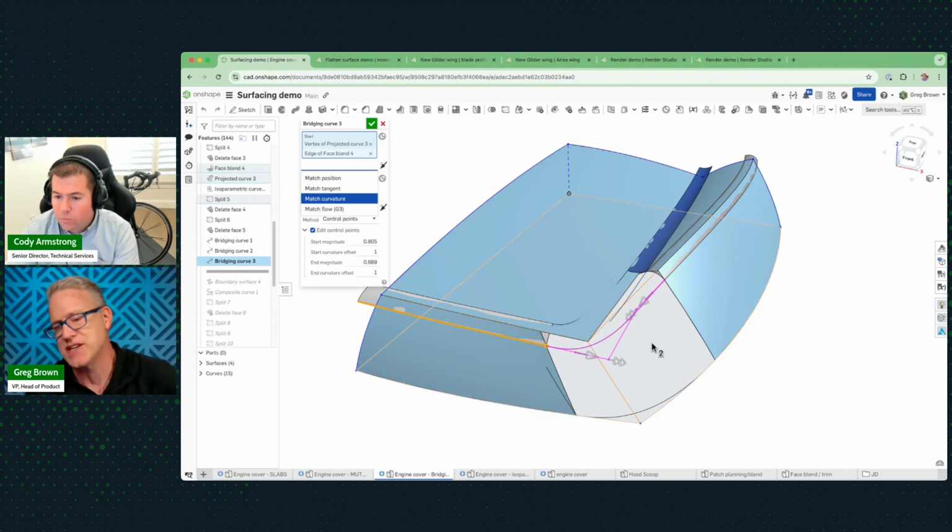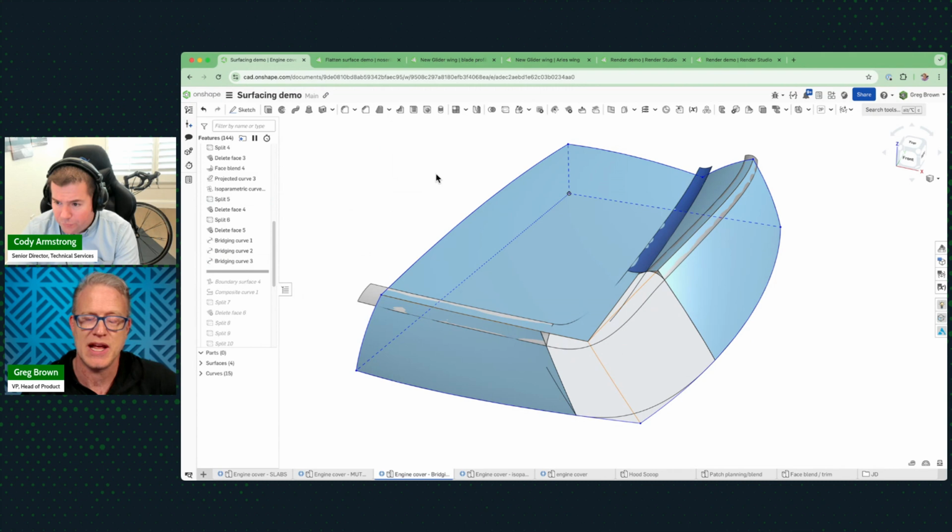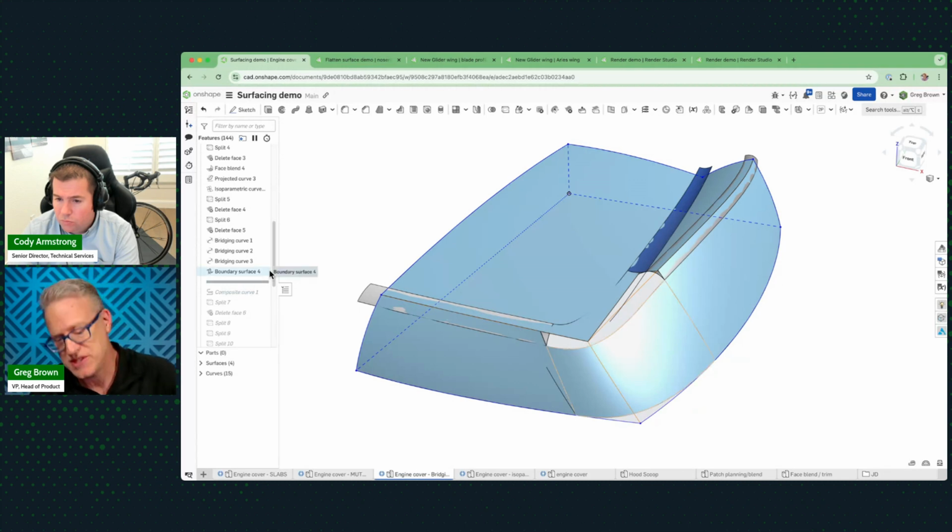So what this does, again, a very, very simple, short explanation for a complicated and highly technical topic, is that it adds an extra control point, and it raises the degree of the single span Bezier curve that we're creating in here. Probably used a lot of words that you might have to go and look up in Wikipedia or somewhere, but the fact that we can do this now enables users a lot more control over the aesthetics of the geometry. And these things all go together.